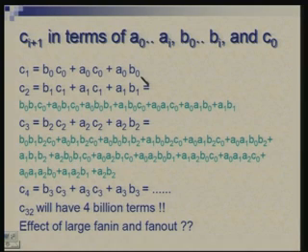So, our objective here is to keep the level low, the number of gates in a chain low. So, we expand it and we get a 2 level expression for C2. Next we take the expression for C3, and take the value of C2 from this expanded form and substitute it here. You get again a large expression, but still it is possible to get a 2 level expression. One could keep on doing this.